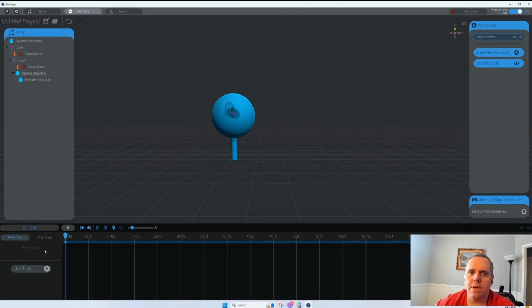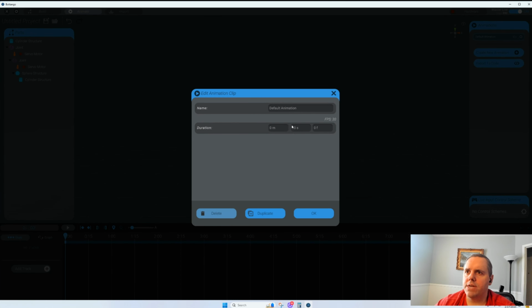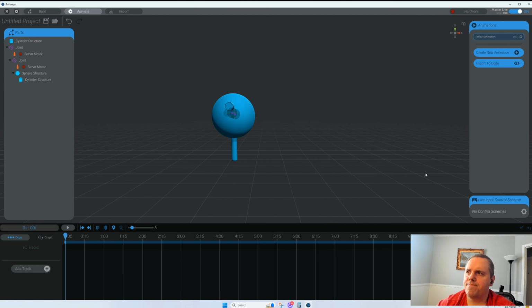Alright, so here's your animation track, I guess is what you'd call it. This is for 10 seconds. If you want to change that, come up here to default animation, click on that, and you can change the seconds here. We'll do 15, but you can do 30, you can do minutes, whatever. Let's just do 12. I don't want it to be real long. So, okay. And now it's extended out to 12. You can do 20, 30, whatever.